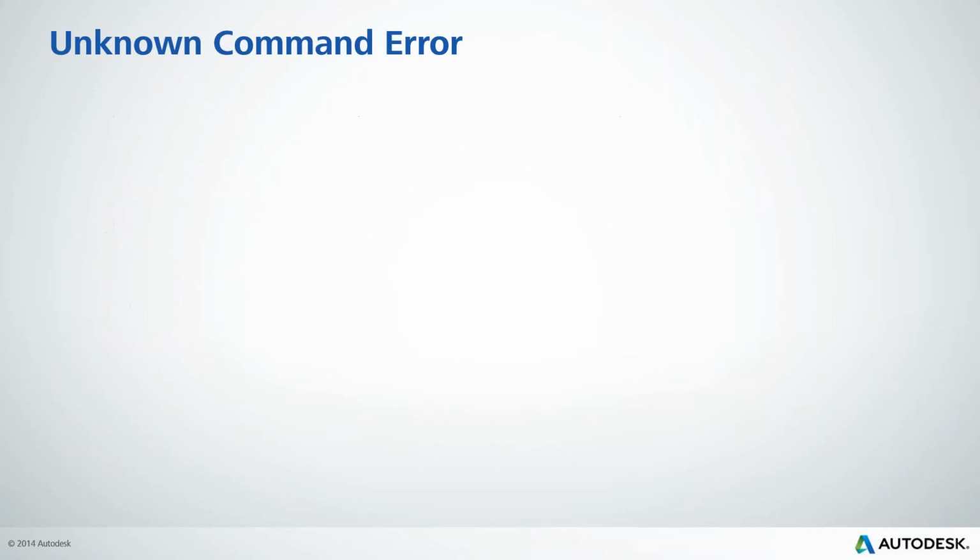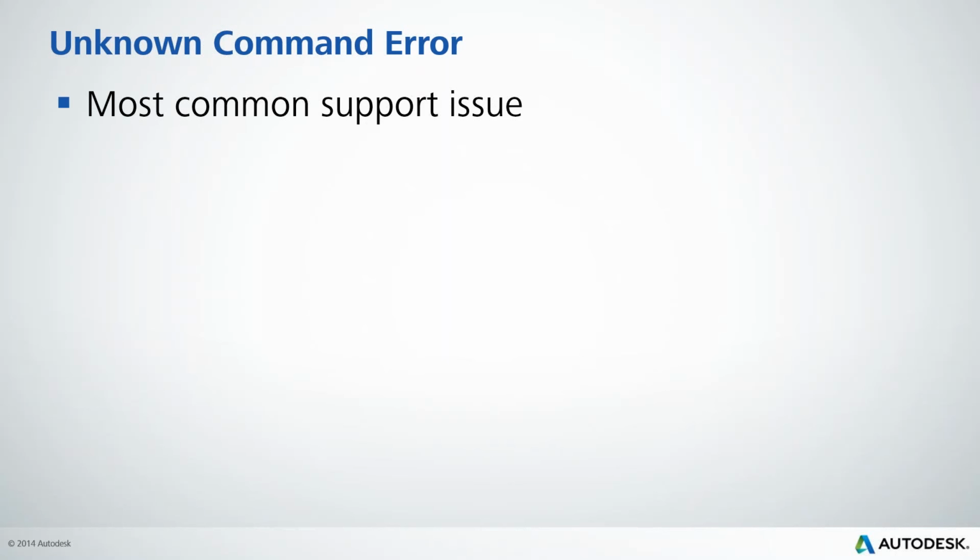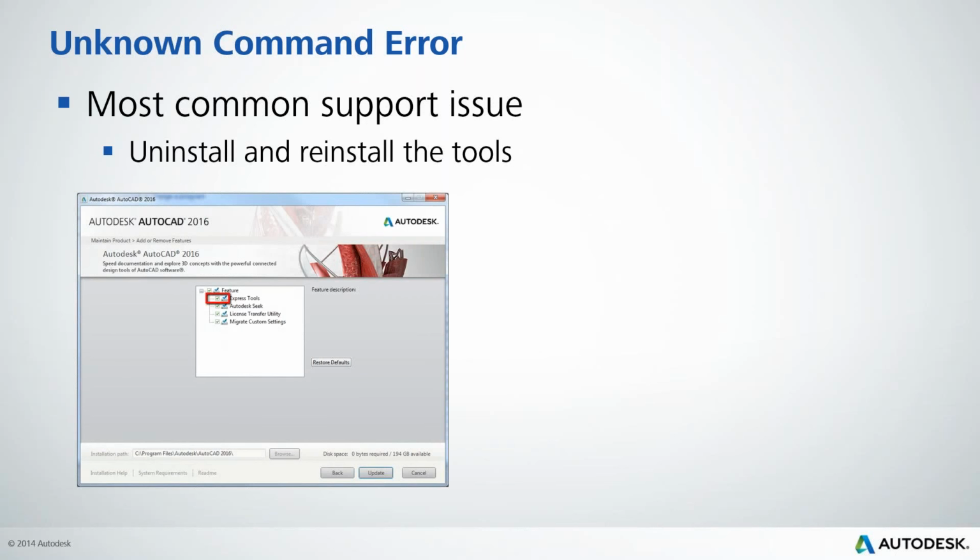Okay. So the unknown command error. This is, like I said, the most common support issue that we get. The Express Tools menu shows up. You're trying to use one of the commands, and you get unknown command. And the most common way to fix this is to uninstall and reinstall the Express Tools.